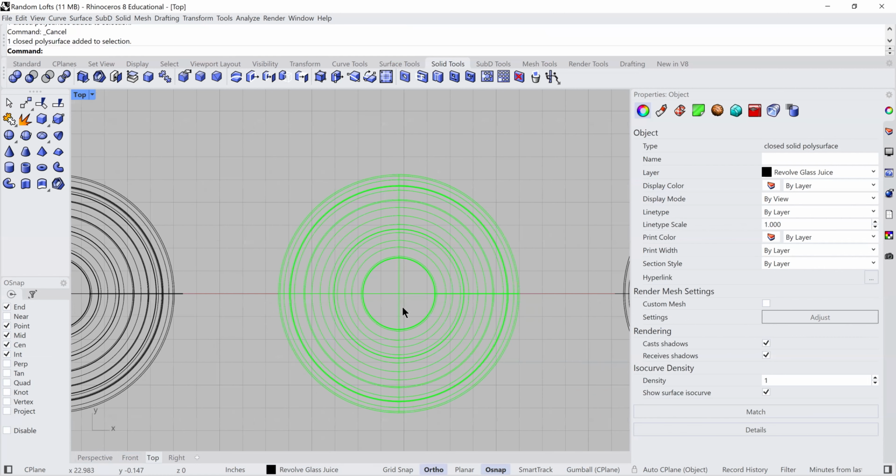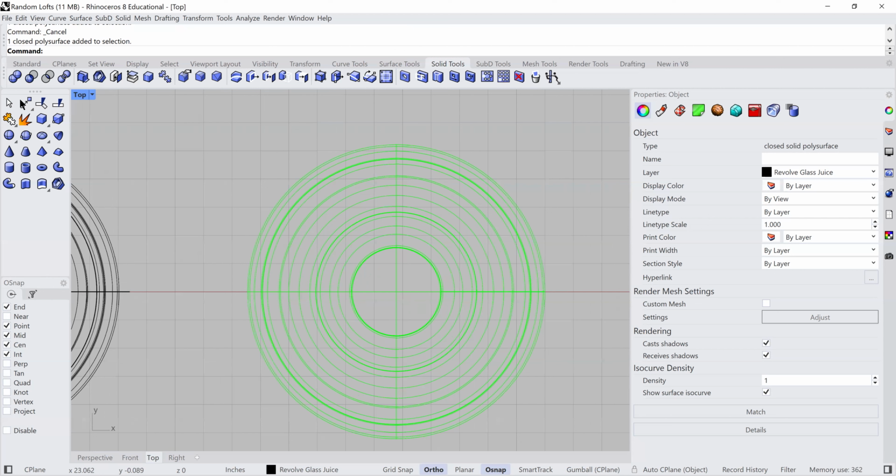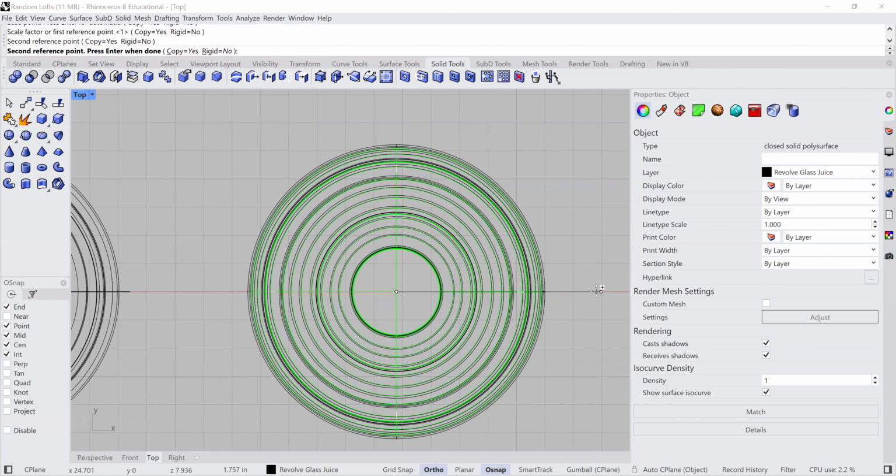If it touches that wall, we're going to get these random artifacts where the two materials are actually touching one another. So in 3D modeling, that's an anomaly. It doesn't really happen. So we need to separate that slightly. And I'm talking very, very slightly. So I'll just demonstrate what I mean by that. I'm just going to go to 100% scale. And let's do a copy. Yes. So I'm going to snap to the center. And I'm not snapping here. Snapping to the center. I'm going to come over here. And I'm just going to move that in just a little bit.